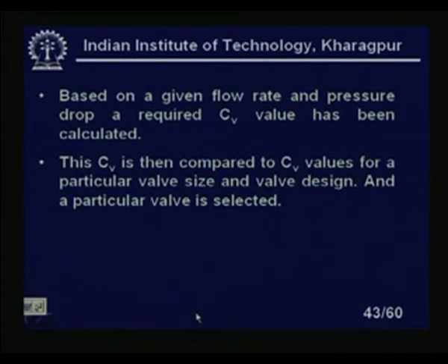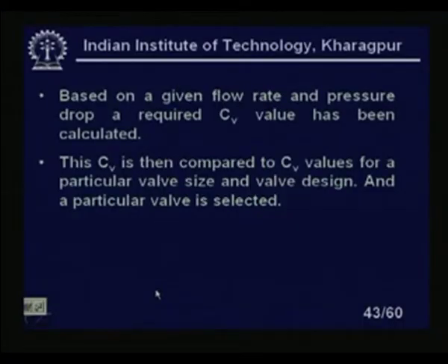The Cv is then compared to the Cv values for a particular valve size and valve design, and a particular valve is selected. From the series of valves we have, we have to select a particular valve. First we will calculate Cv and compare it with the standard Cv of the available valves in the process. So we will choose a particular valve whose Cv will match the Cv which you have calculated.